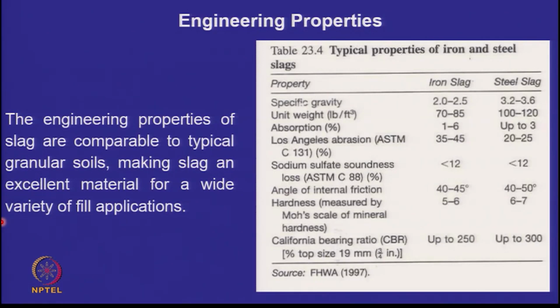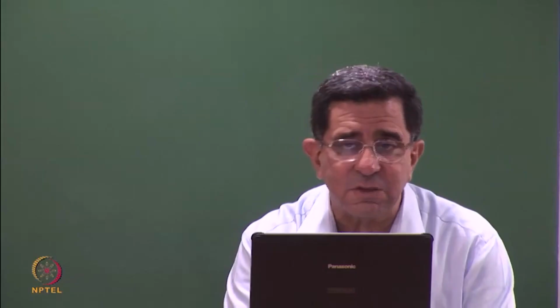It's a good material. What you don't get from both these tables is the grain size distribution. When you look at something as a soil, I can't adjust to it until I see the grain size distribution. Just remember, it's a mixture of various grain sizes: sand, silt, gravel grain sizes.